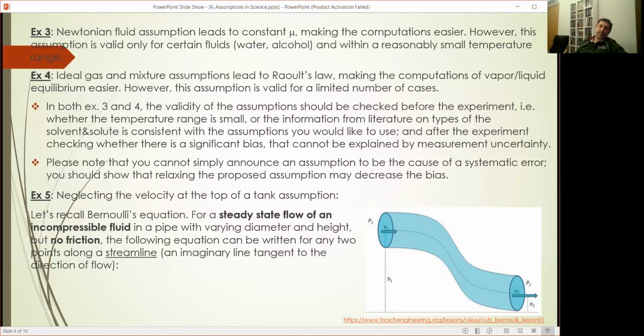I don't know how much we have covered these in the fluid dynamics course. There are streak lines and streamlines. Under steady state they are all the same, but when not at steady state, they are not the same. But very basically, between two cross-sectional areas we may use this equation. Note that here 1 and 2 do not refer to anything related to time, because we are at steady state. At steady state, 1 and 2 correspond to two different positions. Here 1 may refer to the entrance and 2 to the exit, but as I said, these may be anywhere if you just take a cross section here.